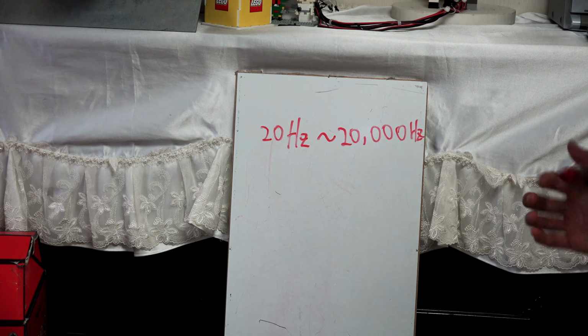There is a function pulseIn, so we can find the duration of high with pulseIn, comma, the echo pin, and high.